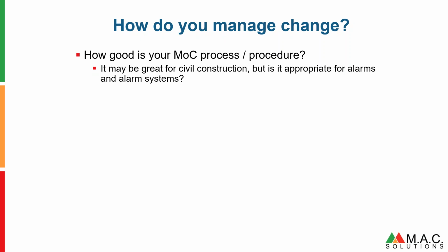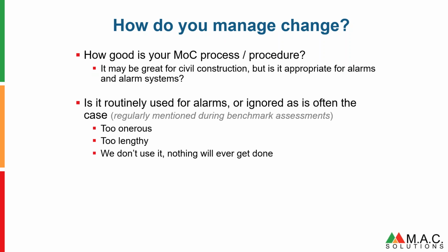If I want to change a set point on an alarm, how do I go about doing that? Is my management of change appropriate for managing alarms and alarm systems? Quite often, the answer to that is no. When I do benchmark assessments on alarm systems, regularly, operators, maintenance staff and supervisors in control rooms tell me that they don't use the management of change system because it's too onerous, it takes too long, there are too many steps to take.